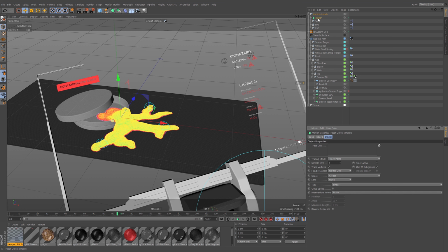Sometimes you want to be careful with that. So I'm going to have point 1 to point 2, and I don't want it to trace all paths, I want it to connect them up. So connect all objects, that's perfect. I also uncheck trace vertices, because there are no vertices here, and sometimes that doesn't work, so I turn that off.